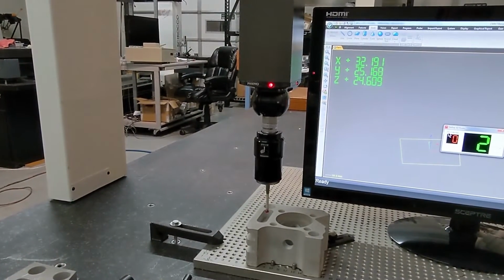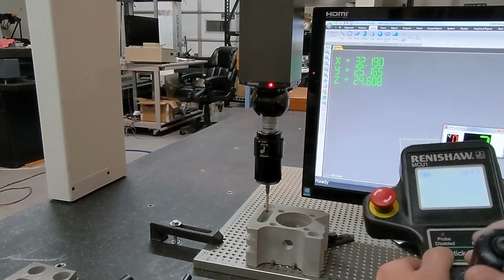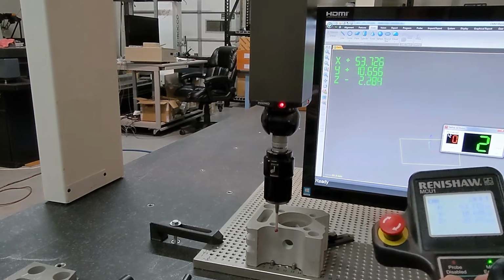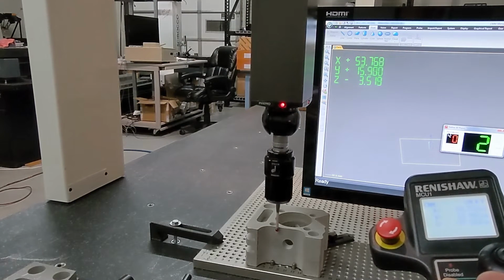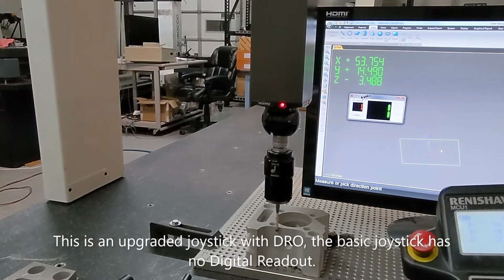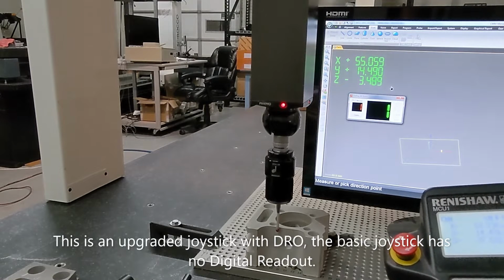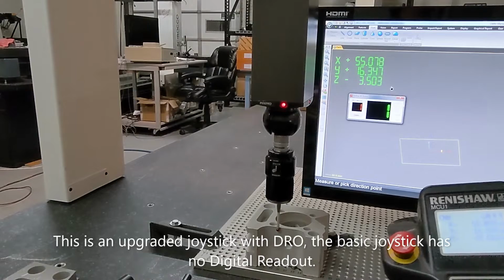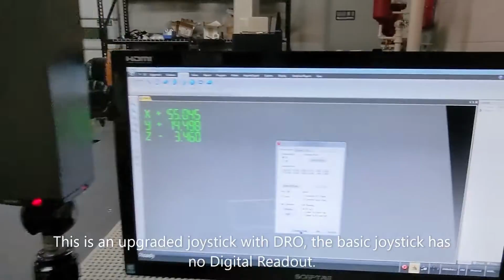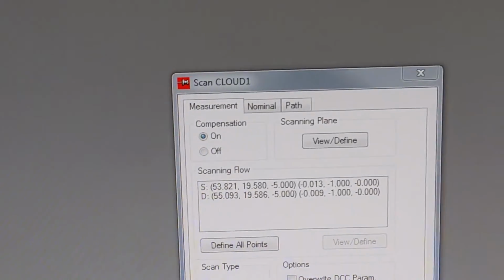And so I'll use the joystick here to just drive the machine, and I'm just going to simply come to the front of this little pocket, and I'm going to give it a start point, and you can see the digital readout, or the status window, is saying there's 1 point taken, 1 point left. Then I'll just move over and take another point, and that just tells it which direction I want it to scan in. So you can see it assigned those coordinates inside the window here.